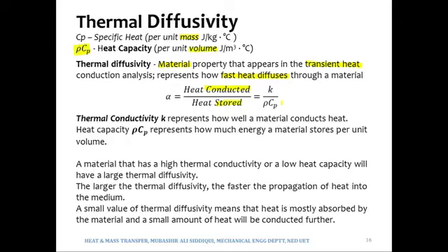The temperature of the pipe will start increasing from 30 to 40 to 50 to 100 to 150 degrees Celsius. And how is the temperature of the pipe increasing? Because it is getting energy from some source, and that source is steam, and the pipe is in fact storing energy. So whenever there is storage of energy, the temperatures will not remain the same. Whenever there is a storage of energy, either in negative terms or positive terms, the temperatures will not remain the same. This is a very important point.